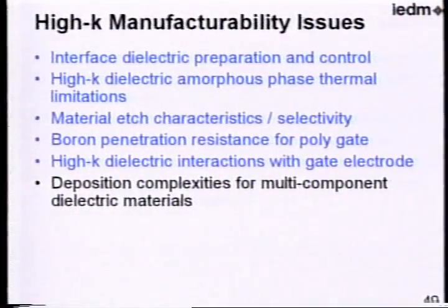Some of these depositions to make these, some of them are put down with PVD, some down with MOCVD, ALD, various types of depositions. Every one of the depositions not only has complexities associated with it, but they also end up with different results. So you have different characteristics of the films depending on how you put them down, even in terms of mobility and so forth. Conformal depositions, of course, if they become non-planar, you have to contend with that, and especially over corners. Metrology, of course, of these films becomes an issue.